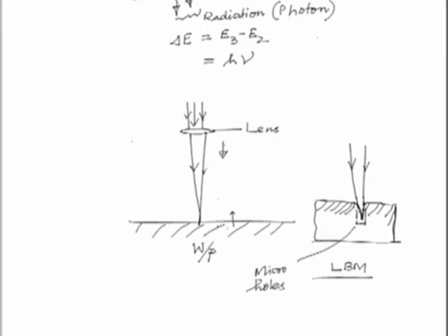like in this case, this area wherever we are machining. So, near to this area may get affected further, or we can say this zone on either side of the cut can be considered as the heat affected zone, where the property of the metal or the alloy can be different. This may not be required or appreciable in certain precision application cases.